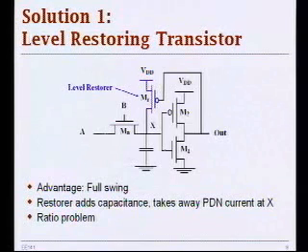So I can have one big chunk of pass transistor logic, and then I really have to worry about how I can interface these reduced output voltages to static CMOS. One way is maybe we can use that ever so important concept of feedback. I'm sure in 140 you're having so much fun with it. We can use that to restore the signal.